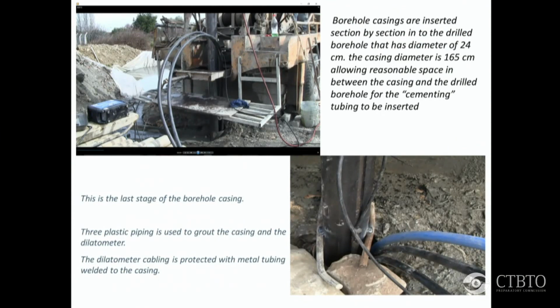The next phase, of course, in any borehole is the cementing or grouting of the borehole. In this case, unlike all the other boreholes, where the borehole tends to be grouted from the inside outwards, we grouted from the outside inwards, so to speak. We used effectively 3 plastic tubings which were attached to the outside of the casing as it went down. 2 of the black ones you can see here were all the way down to about 150 meters. And then the blue one was left halfway, about 75 meters.